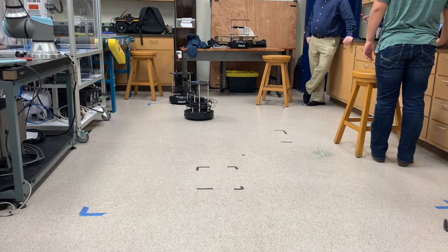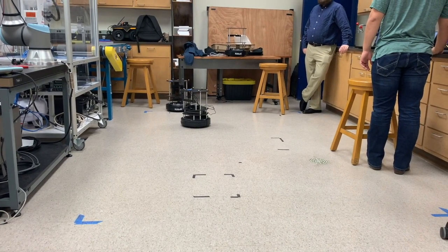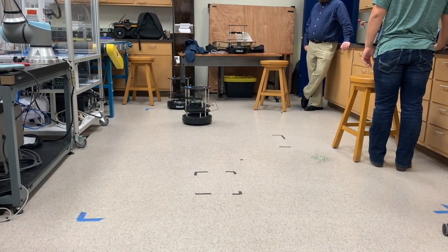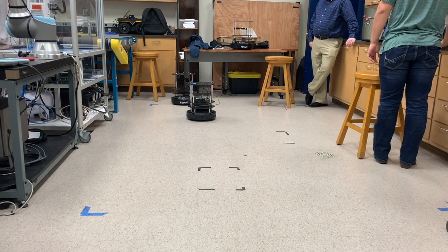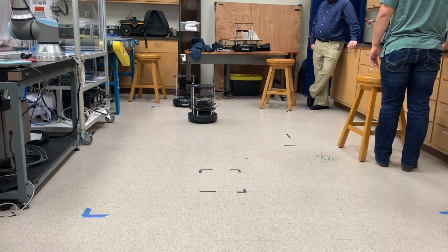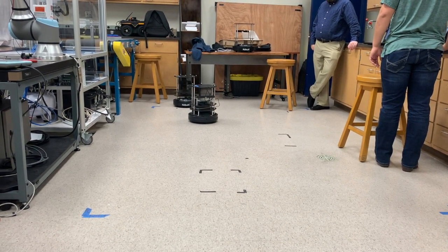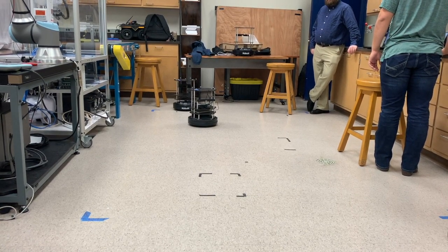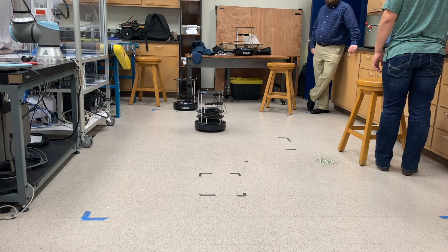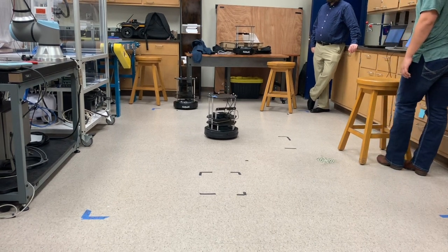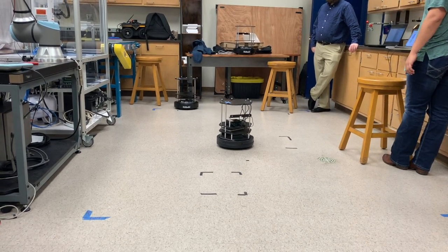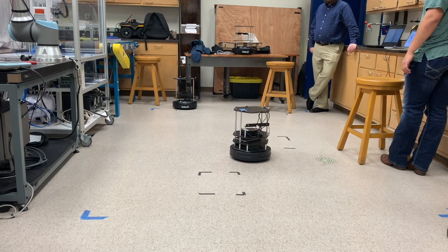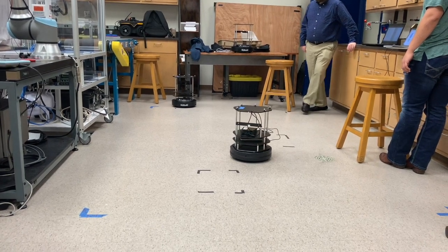The final algorithm rotates the Turtlebot slowly until it is facing its inputted destination. Once it is in an acceptable angular range, it slows down even more and then comes to a stop. The algorithm then makes it move forward until it reaches its destination. And finally, we decided to add a spin at the end to prove that the code worked correctly.